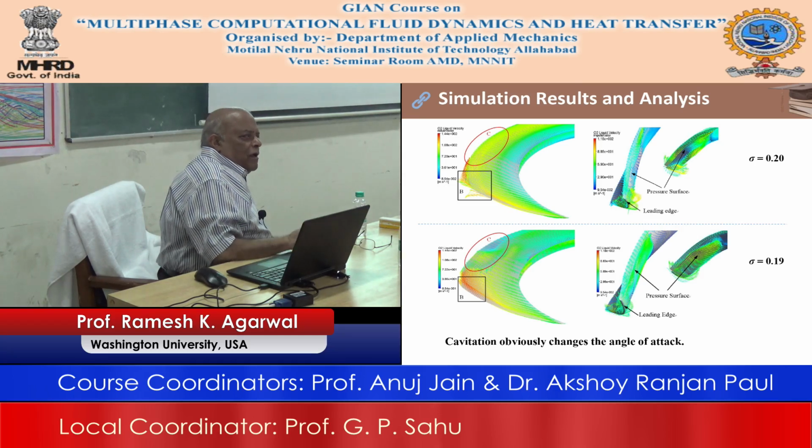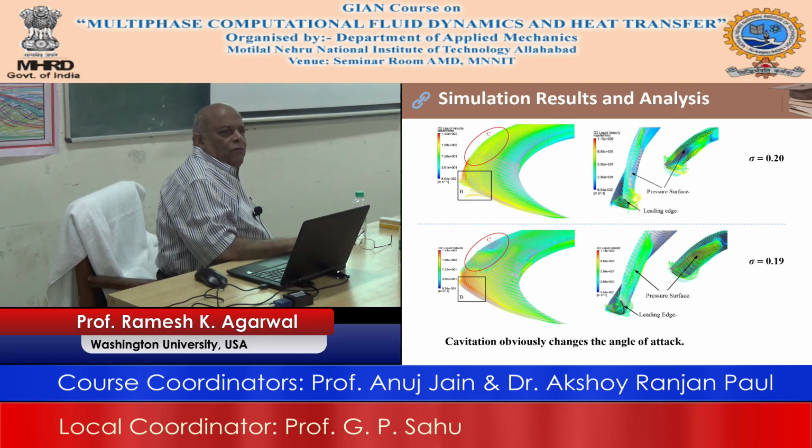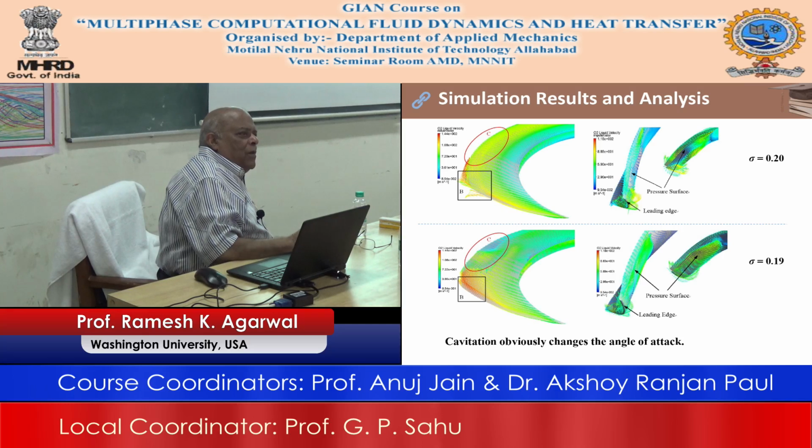It's a planar flow, rotating about the third component, that is, in the z direction. What is the equation of vorticity? Anybody remembers? Curl of velocity, that is correct, del cross U. If you simplify that, it turns out to be dv/dx minus du/dy for the z component.